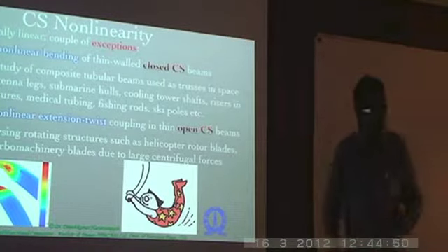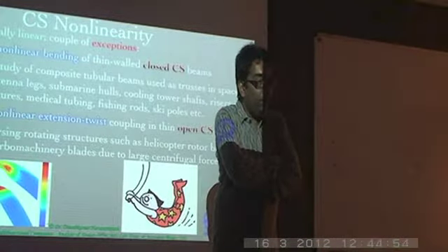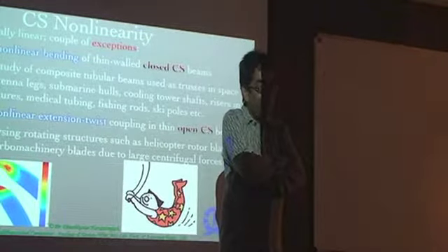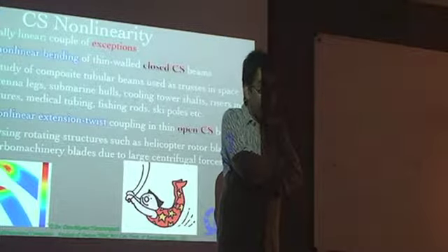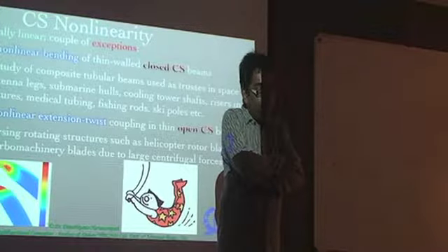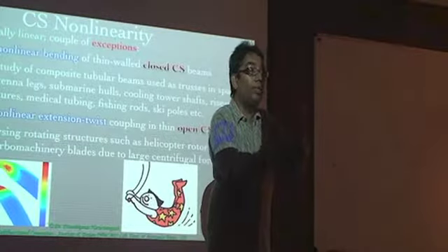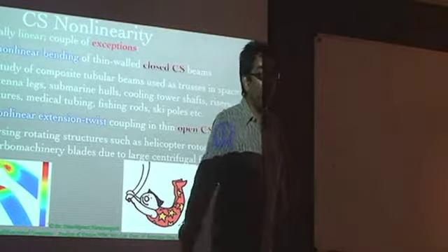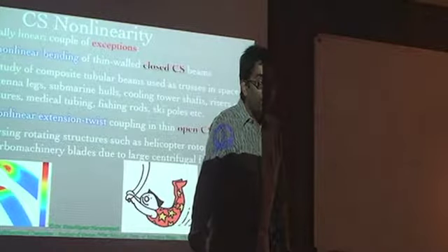Same thing, sir. Yeah. Actually, this thing is very prominent. Along the beam length, we'll do the cross-sectional analysis. That's okay. Yeah. Then 1D analysis will be done using those properties of the cross sections throughout the beam. For a particular point load, we can only do 3D analysis. Just around that point load, to find out what is happening, you have to do a 3D analysis. That's what we are getting, 3D relations. In our recovery itself, we are getting 3D relations.